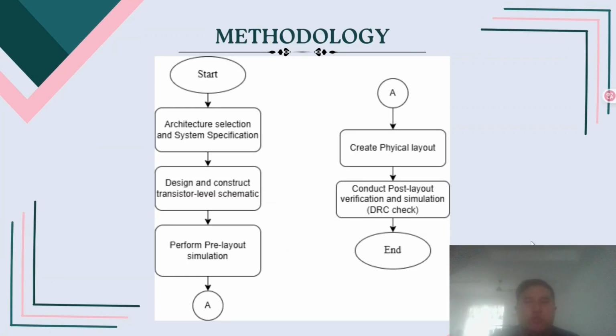Today I will present the structured approach used in designing a CMOS-based flip-flop. The process begins by defining design objectives, focusing on power efficiency and speed. The flip-flop was selected due to its reliable edge-trigger functionality, making it ideal for synchronous digital circuits. Next, the circuit is designed at the transistor level, ensuring optimal transistor sizing and configuration. Special attention is given to minimizing propagation delay while maintaining low power consumption.